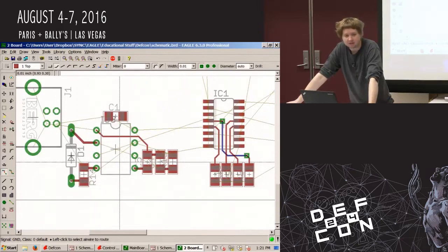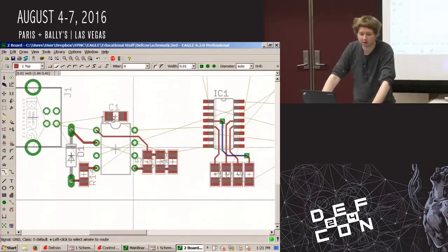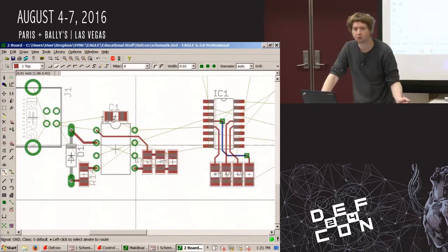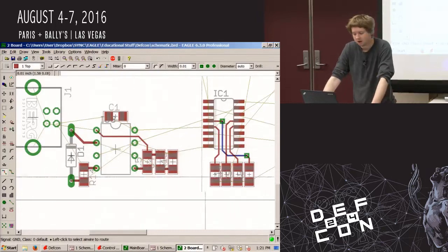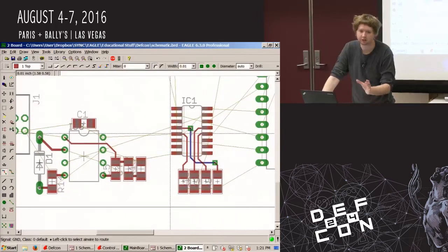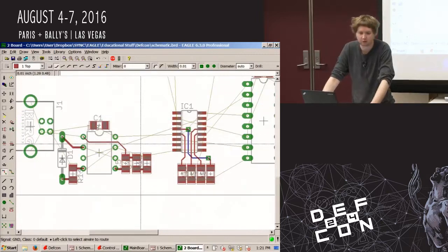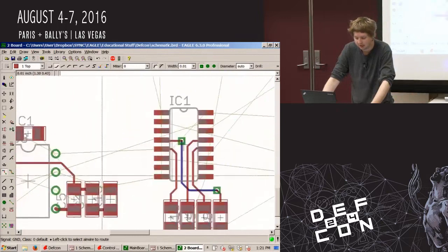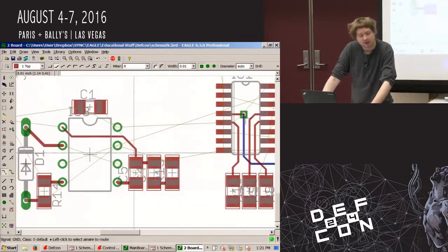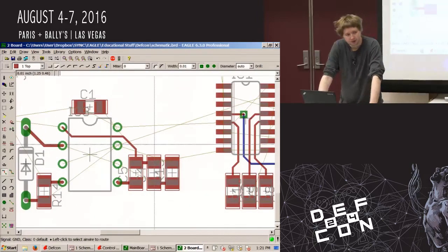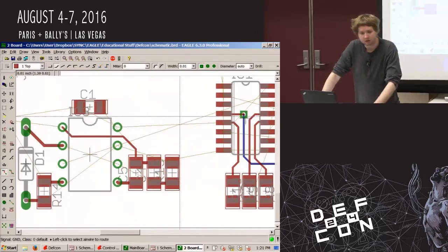It has various calculators in it, including a how much power can your trace take calculator, and it'll tell you, like, if you want only a 20-degree rise during full current, then this is the trace you need. Very handy tool, and I have it out when I'm doing most any of this stuff. Droid. So I think there's a free version, but then mine.